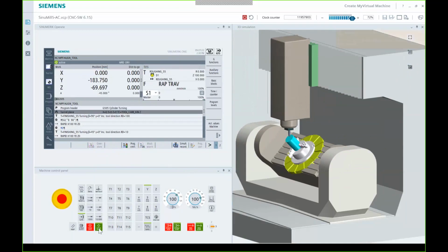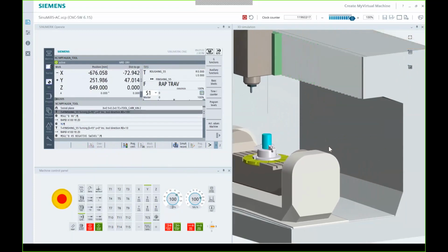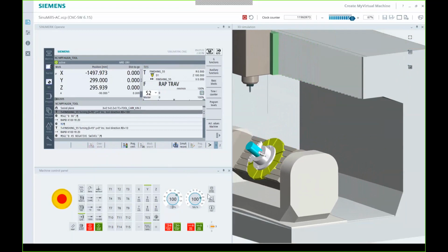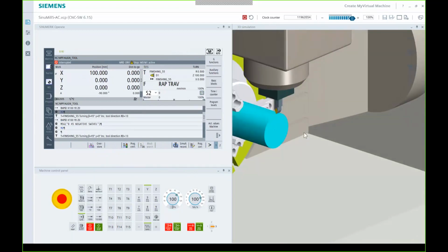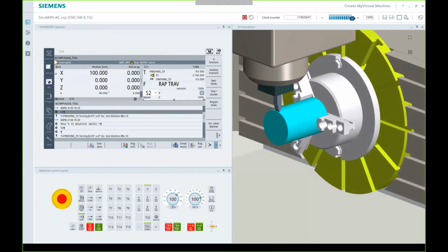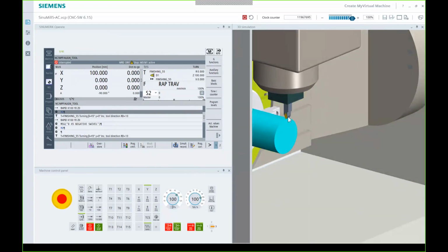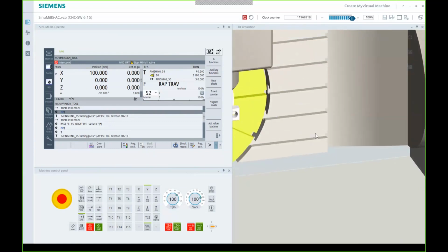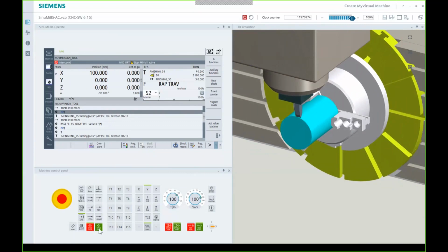So it's going to come up, change to a different tool. Now it's coming down, and now that tool is right up against the edge of the part. And take note, this is the first position, so this is B90. Take very clear note of where that insert is, because we can manipulate that by using the spindle direction.